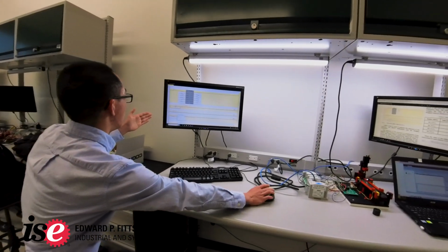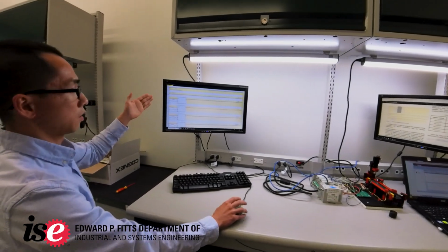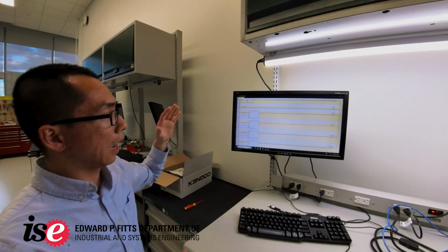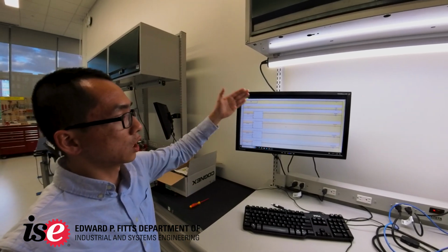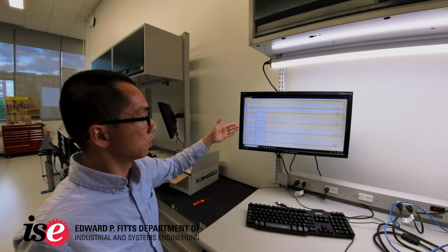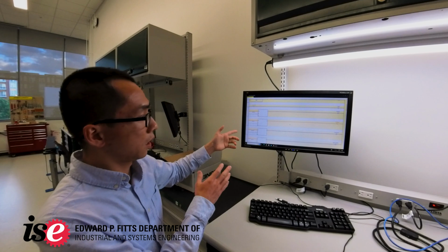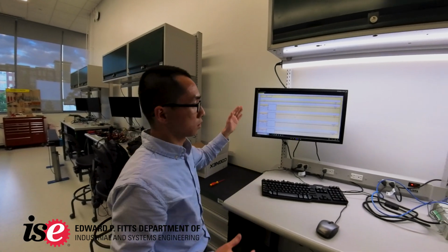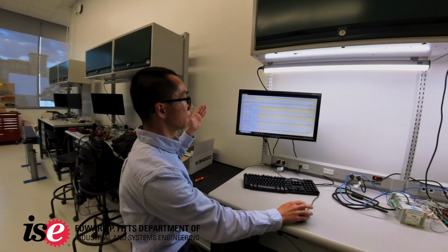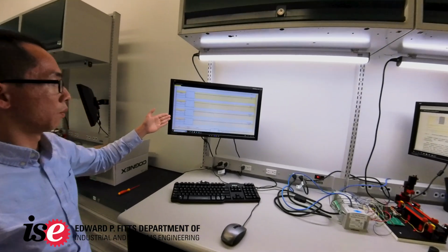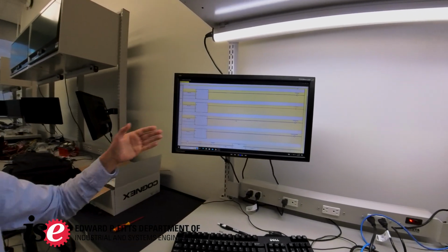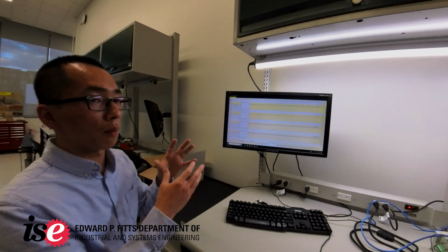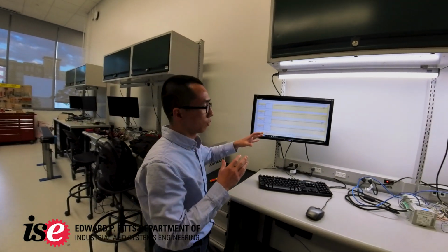So the next few lines are about the Modbus. When the Modbus changes the variable MB int, it will change the speed. And if the Modbus changes the variable at address 3, it's like the emergency stop, so it will stop the motor right away. And the last one is when the Modbus variable gets changed, it will reset the counter that we use to count how many items have passed through the conveyor belt.